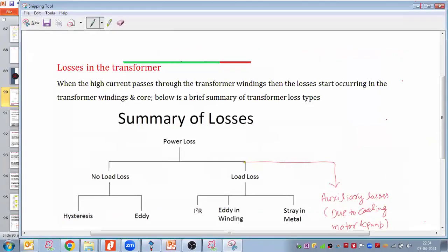We discuss about what kind of losses occur in the transformer, right? Then we discuss that whatever rating I am telling, this is rating of HV and rating of HV and LV. Means if I am telling you 4 MVA transformer, it means 4 MVA is my LV power and 4 MVA is my HV power, right? And this transformer cannot be connected with a 4 MVA or 4 megawatt load. The reason why it could not be connected, I hope we discussed and it is clear.